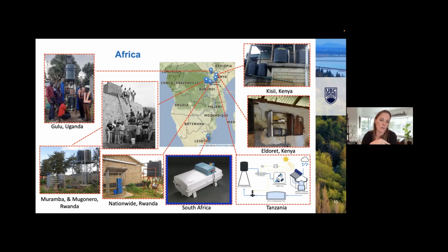And they also had multiple UV lamps in parallel, so they could choose which one to use. They could choose a smaller lamp for low flow rate and good quality water, high UV transmittance, meaning more of the UV actually reaches the target microorganisms of concern. But they could also use a larger lamp if they had more volume or worse water quality. So that was something unique to that system.